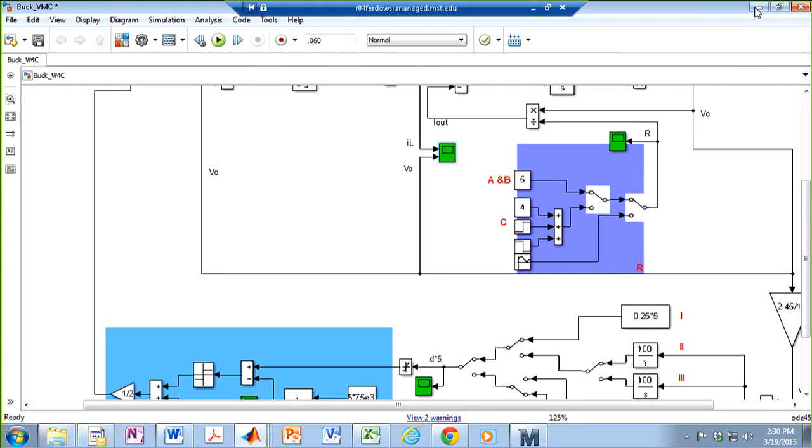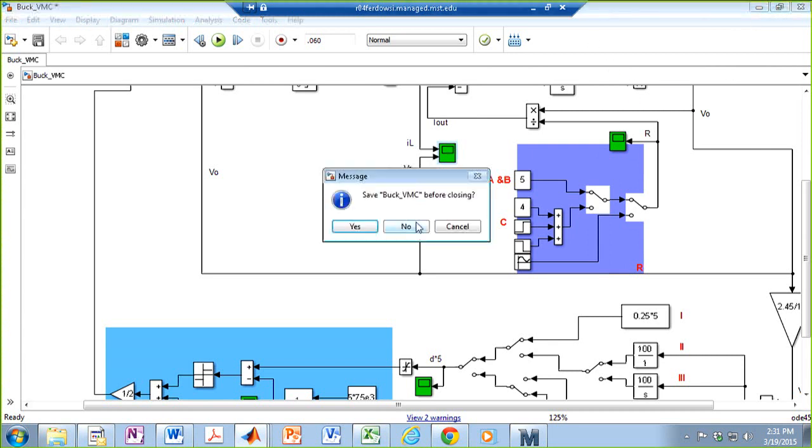If you have a very small load, your converter is going to go to DCM to begin with. So everything that we have said is not holding anymore because it's DCM. But remember, you expect your converter to consume some load, some power, because otherwise it doesn't make sense. You're saying that my inductor current, which is my load current, should be 2 amperes, and you don't even have a load. So where is this current going to go? It's going to charge your output capacitor. So your output capacitor is going to get charged and charged and charged until, if this is a buck converter, it is going to get to 48. And then you're in DCM. Actually, we can do it, and you can see what happens.